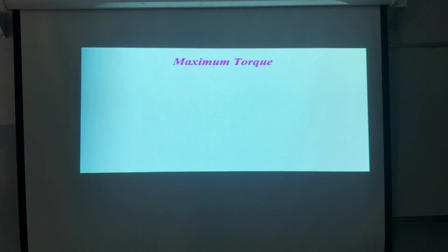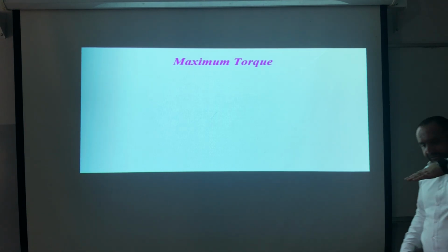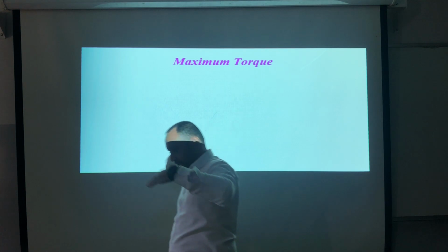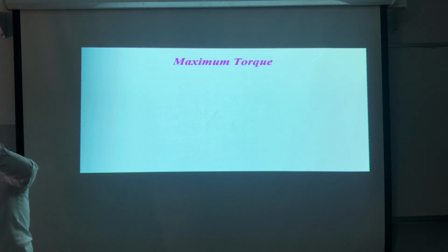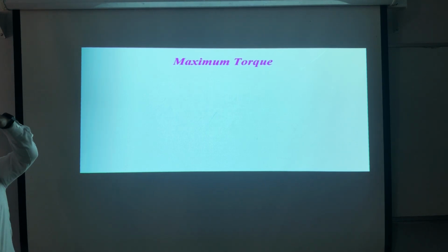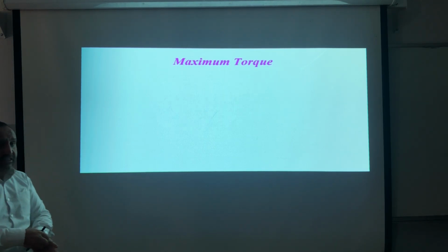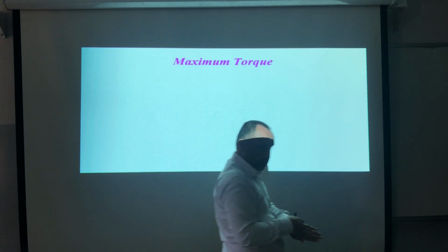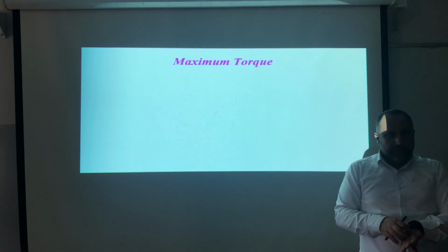Now, how to find the maximum torque? Until now, we specified the relation between the slip and the torque at high slip and at low slip. So now we have a plot for the linear and the non-linear. Now we need to find the intersection point to connect the two graphs, which is the maximum. How to find the maximum torque? Take the derivative.